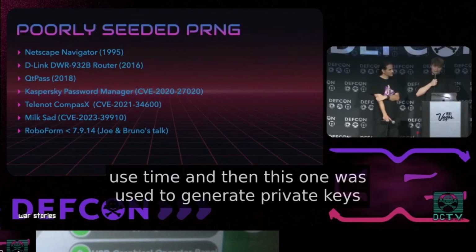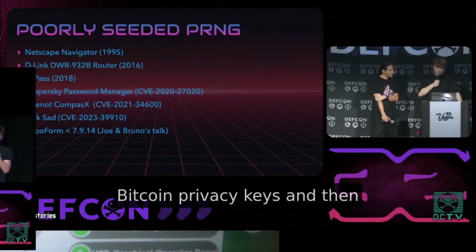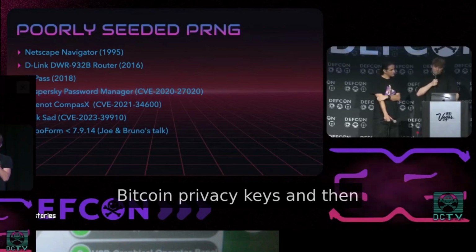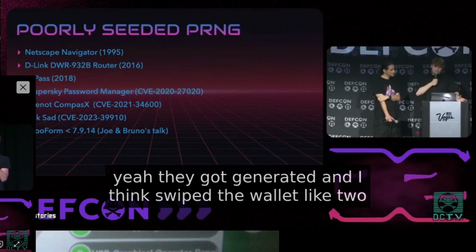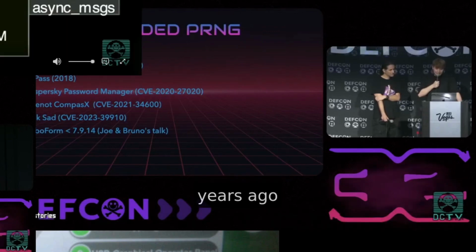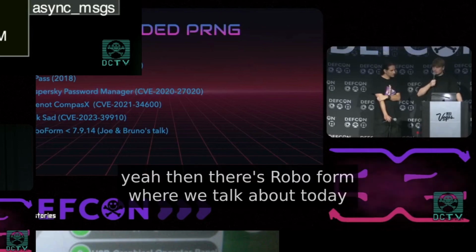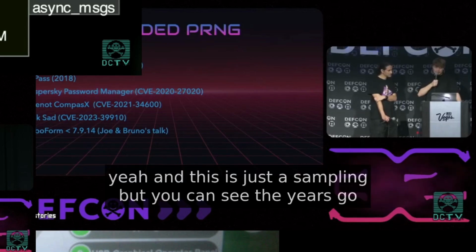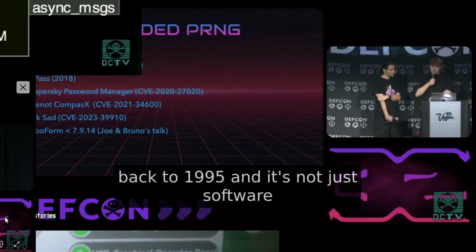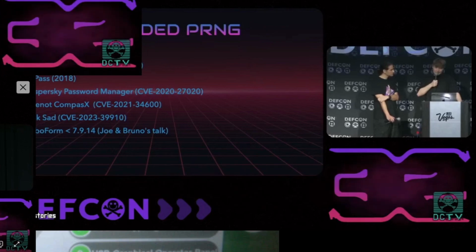The heart of the GNU Radio stuff is, first we start with our USRP source. This pulls in data at a sample rate of 4.8 megasamples per second. Our center frequency is 125.2 megahertz. And then we run this at 200 kilohertz. We're actually modulating at 400 kilohertz. But we don't want to listen to the DC spike, because software-defined radio is going to give you this giant DC spike, and you want to move away from that. And then you filter out that DC spike, and then you can listen to the actual data you want.